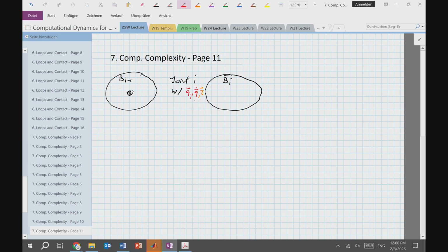Let me space this out a little bit. All of these are just the quantities of the joint. So this is why I call this Qi, Qi dot, and tau I. Written here as vectors because they can be multidimensional, but for a rotational joint, these would just be scalar quantities. The thing that I want to know is the acceleration across that joint.